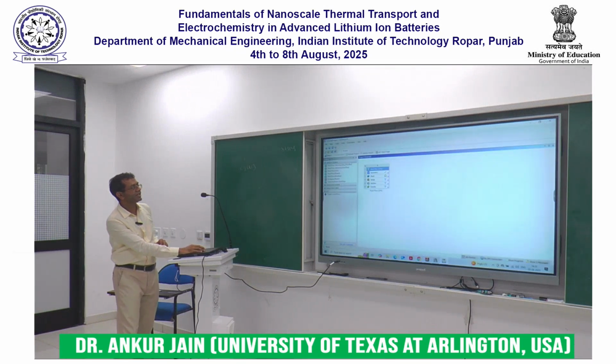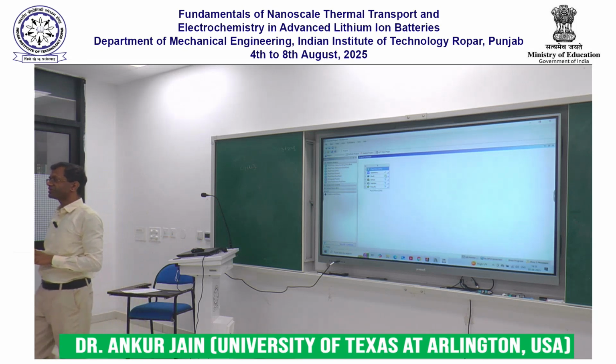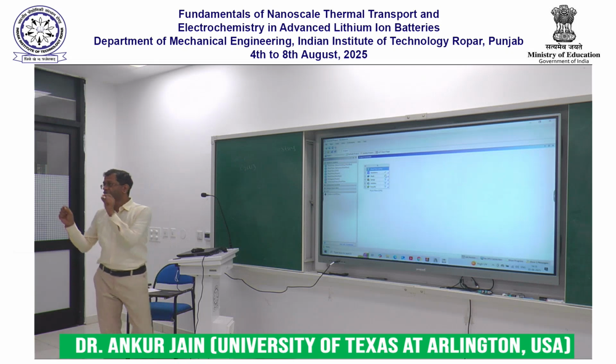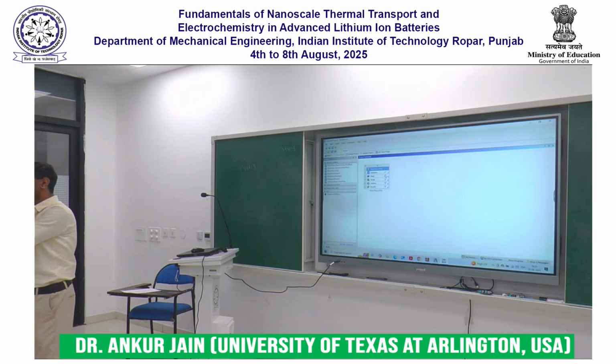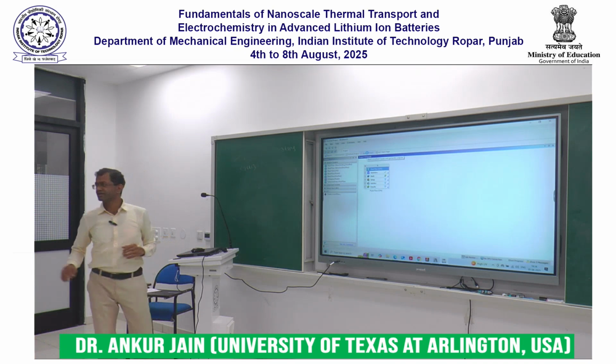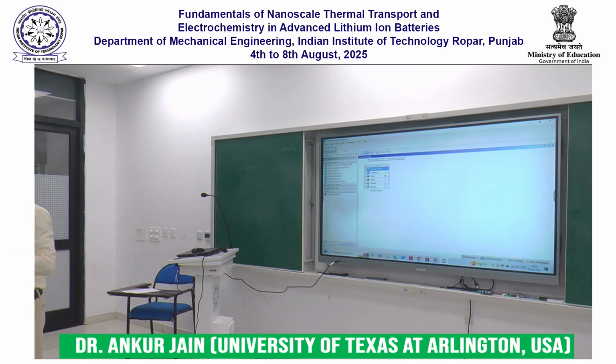So now there is a green tick next to the geometry, which means that Ansys says, good, thank you, I know the geometry that you want me to work on. Next, we need to provide information about how to mesh this geometry, how many nodes to provide in the geometry, and where to place the nodes, and so on. And if you're too lazy, you really don't want to do even that much, you can simply update the project, and Ansys, based on some default values, will create the mesh itself.